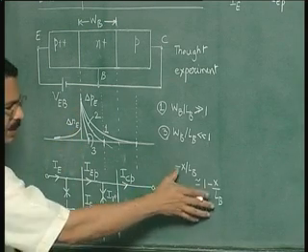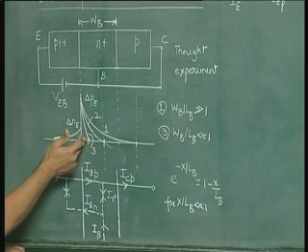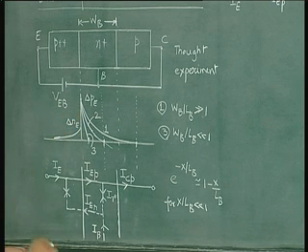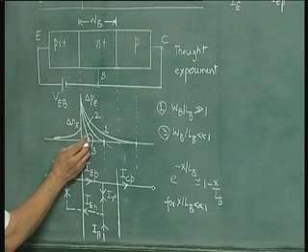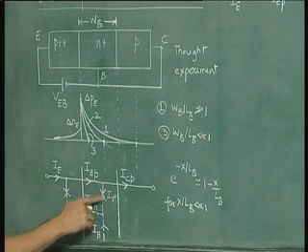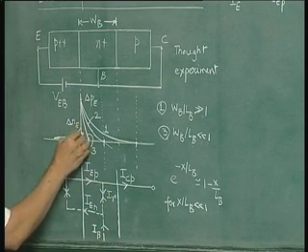So we can see this mathematically, or we can see this geometrically. In fact, geometrical interpretation is much easier to understand and is much more vivid. So for this limiting case of WB by LB very small, the recombination current will be very, very small. The recombination current depends on the area under the excess carrier distribution.